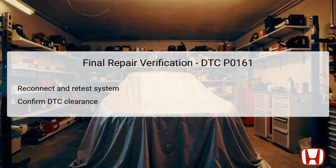After completing the necessary repairs based on the previous steps, the final verification process is crucial. The first action should be to reconnect any components or wiring that was inspected or repaired. Then, a thorough retest of the entire system is necessary to ensure that all connections are secure and functioning correctly. Driving the vehicle under varied conditions is recommended to confirm that the DTC P0161 does not reappear.